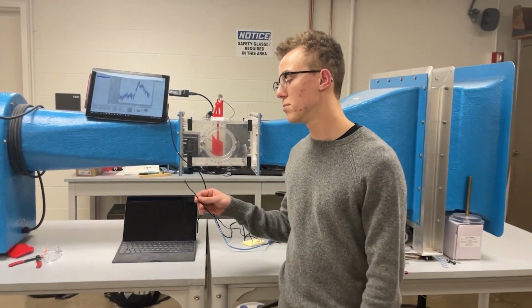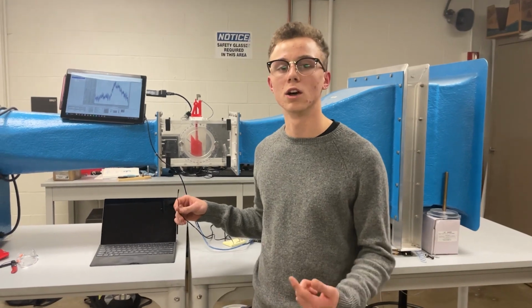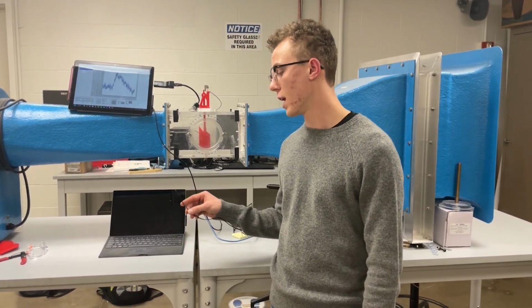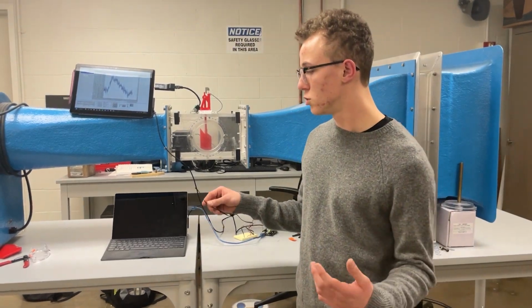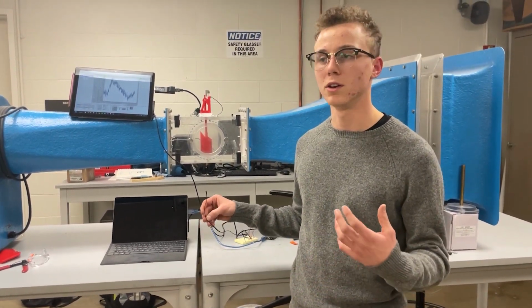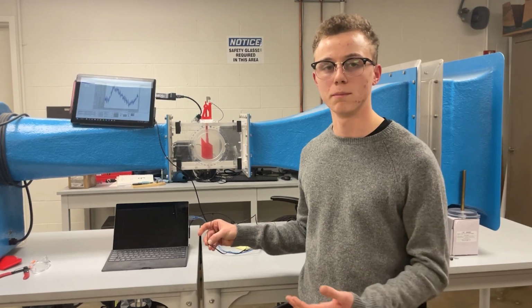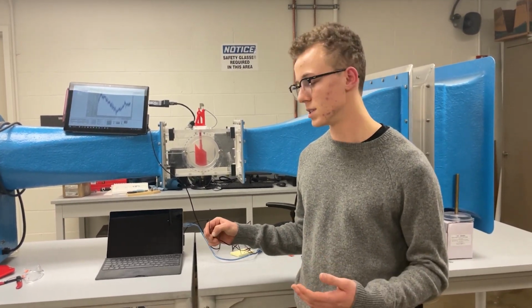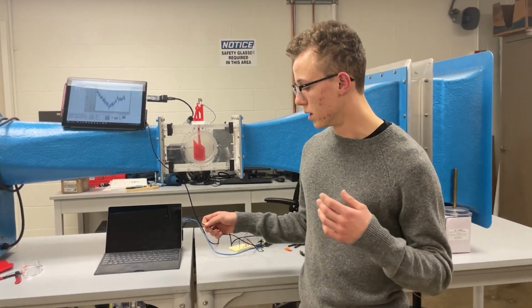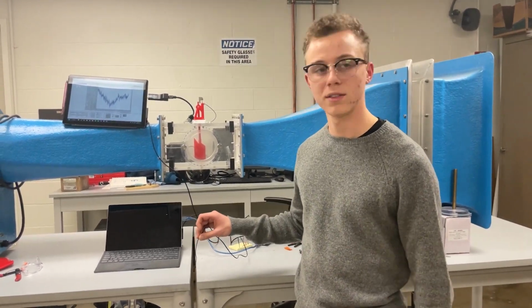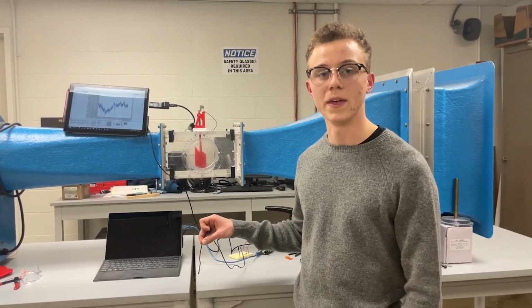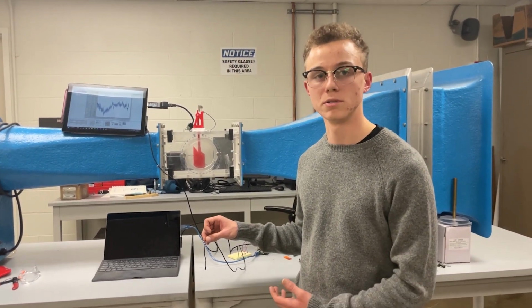We chose the thermistor because we had experience with it, it had a low uncertainty, and it was incredibly easy to calibrate. In order to calibrate it, we simply choose a temperature that we know to be true. For our example, we used an ice bath that we assumed to be 0 degrees Celsius. We put the thermistor into the ice bath, measured the bias that it was receiving at that 0 degrees Celsius, and then took that off from the temperature that it was measuring.